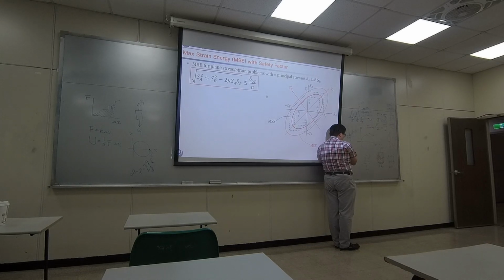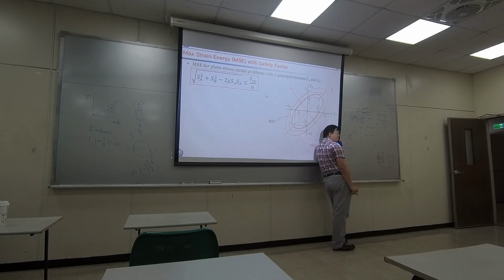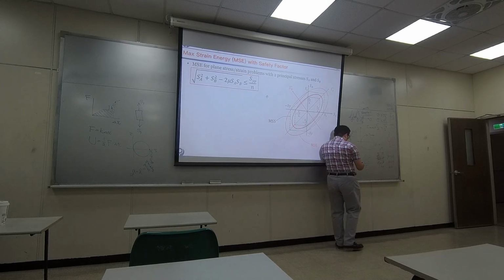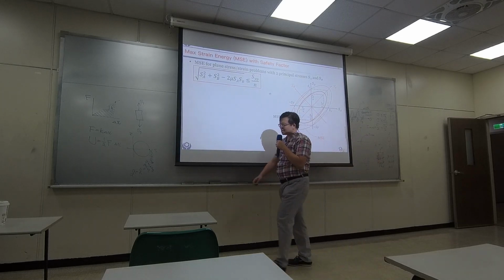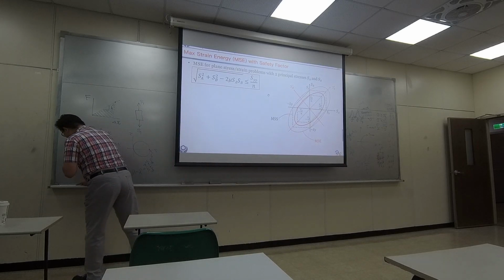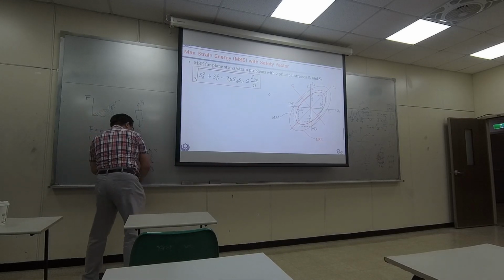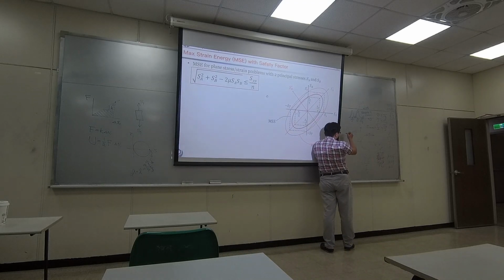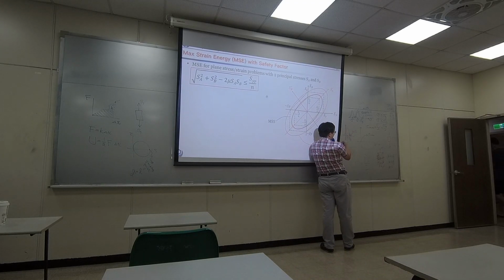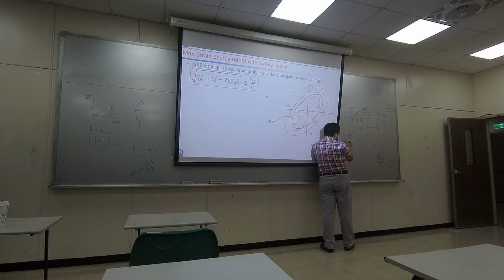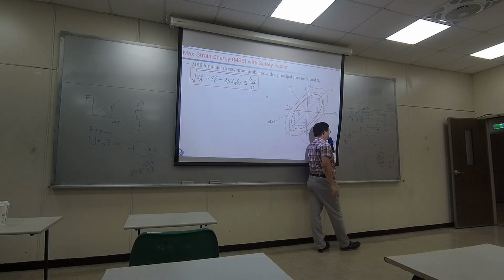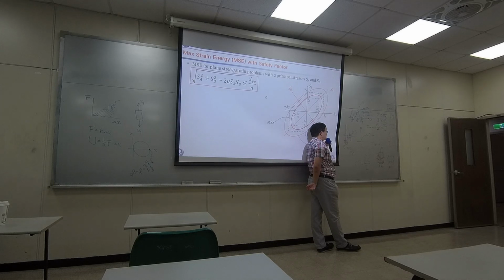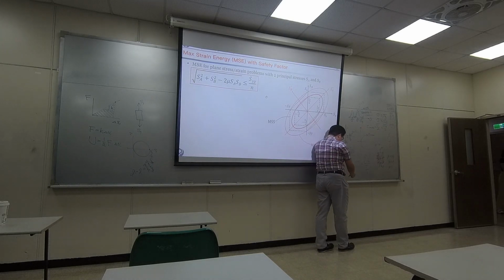They want to divide this value by a safety factor. So they want to limit your design within a range so it's far away from the yielding strength. So there could be an upper limit right here. So this value equals your yield strength divided by n.